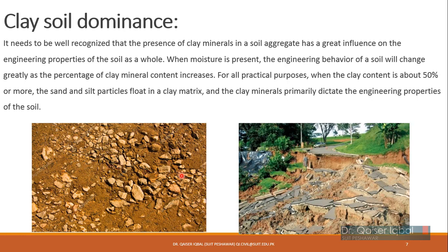For example, you can see a granular soil having clay, with a lot of clay over here, and there is gravel as well. The gravel is a stronger material compared to clay, but here you can see that the clay is almost 50%. If you do sieve analysis, then you will get the exact amount of clay. But if the clay content is even up to 50% in a particular soil, we will have to consider that soil as behaving totally like a clay, because clay behavior is problematic.